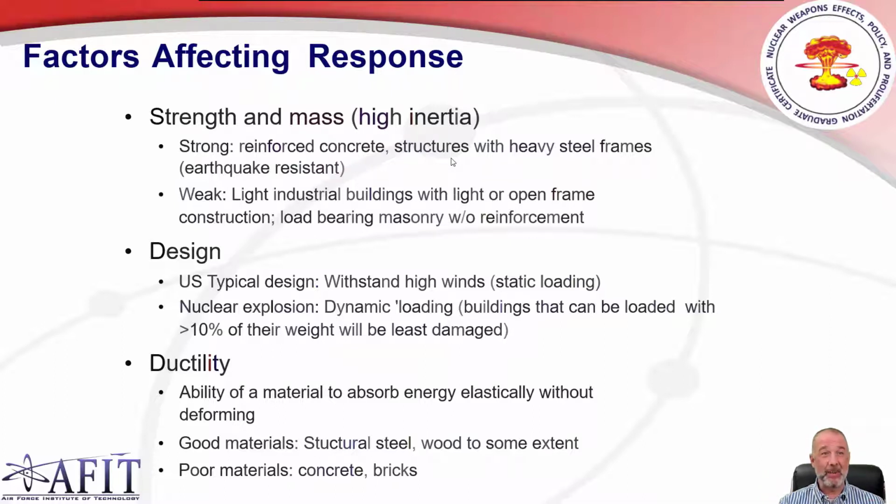These buildings that were specifically designed against nuclear strikes, you can basically push at them with the equivalent of 10% of their mass or their weight, the force that their mass is exerting by gravity. 10% of that can be loaded onto them, and they'll be fine. So really beefy things. And then finally, another factor is the ductility or the flexibility of whatever it is you're looking at, mostly materials that structures are built out of.